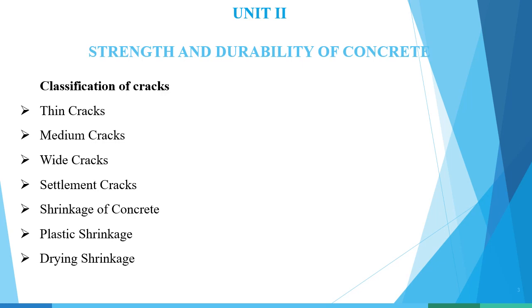The next one, settlement cracks. Plastic concrete settles when vibrated or otherwise. If the concrete is free to settle uniformly, then there is no crack. If there is any obstruction to uniform settlement by way of reinforcement or a larger piece of aggregate, then it creates some voids or cracks. This is called settlement cracks. This generally happens in a deep beam.